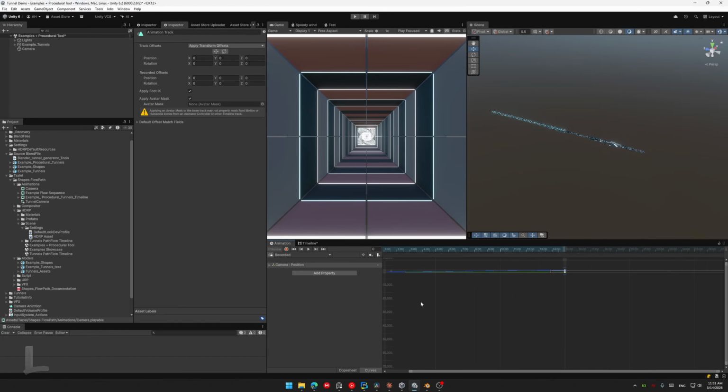Also, something I used in the example is changing the animation curve to delay the acceleration until later. So now I'm gonna do this. Zoom out that way. I'm gonna add a keyframe here and slide that a little down so we're not moving that much at the beginning.